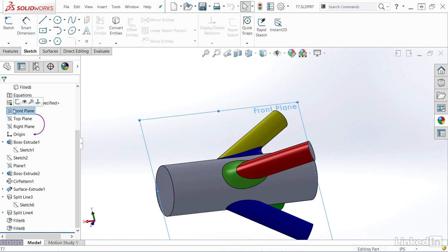In half, and now you have that split line on that surface. I want to do something very similar to the next line here, so I'm going to go ahead and create a sketch on that line. So where's that line? It is inside of here, so expand that out, click on that line right there, and I'm going to use that to create a surface. So click on surface, extruded surface.